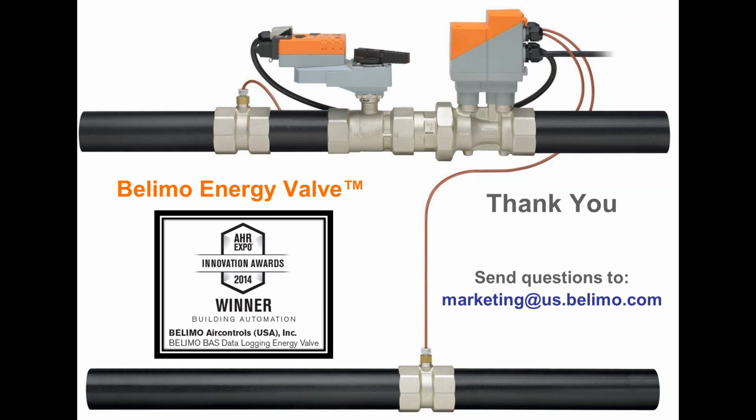Okay. Next question. What is the delta P we have to consider in the energy valve in order to calculate the head pressure pump? Okay, so the energy valve is sold by GPM ratings. In other words, that valve on the screen is like a 2-inch energy valve. I think we can get 75 or 80 gallons a minute through there. But the key is that you can get 75 or 80 gallons a minute through there at 5 psi pressure drop. So you don't need 5 psi to make this valve pressure independent, but you do need 5 psi to hit the maximum flow rate.